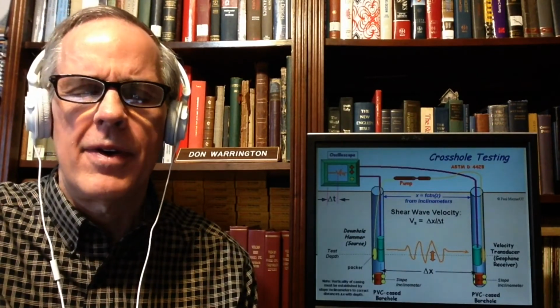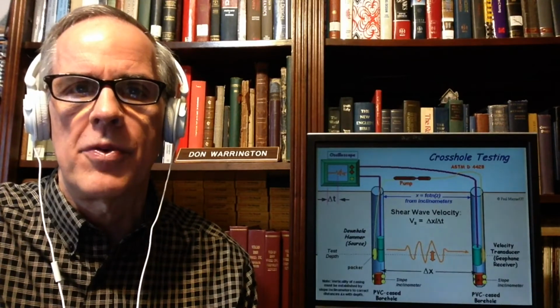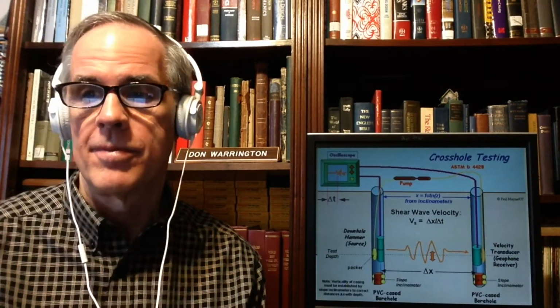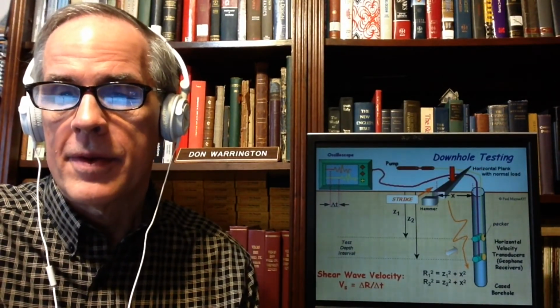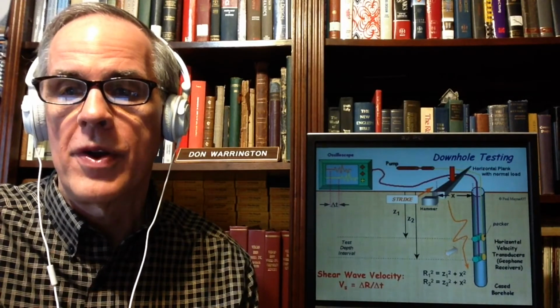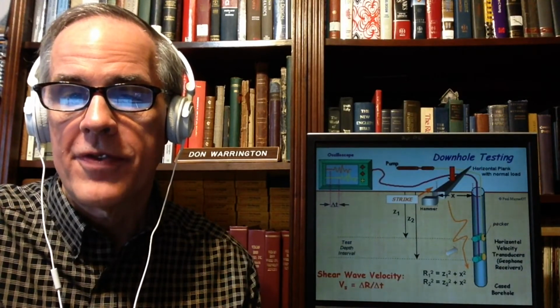A kind of adaptation of that is used with drill shaft integrity, and we'll deal with that when we get to drill shafts. Downhole testing can do the same thing except with one hole and a signal from the surface. But again, it's one way of finding out what your shear wave velocity is in the soil.